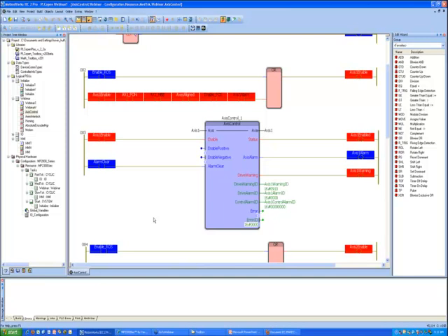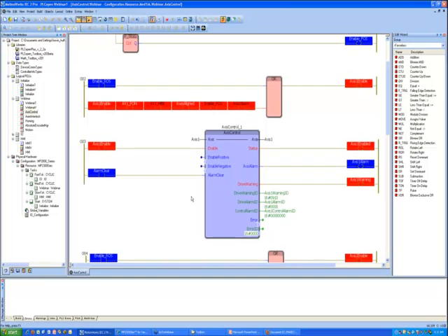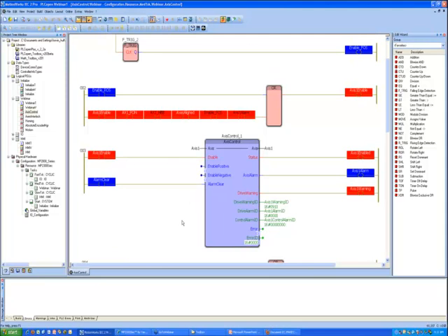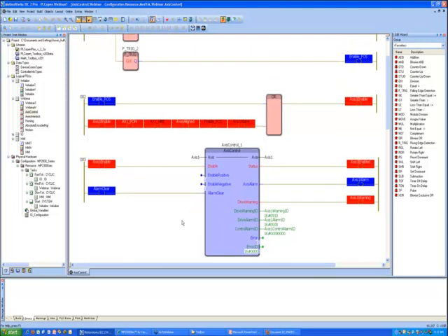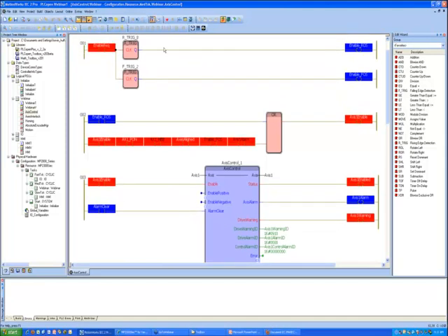And so I'm kind of demonstrating some of the other surrounding interlock logic that's useful for enabling the servo. So I've got some one-shots here that will enable or disable when I change the enable request. And then my logic will keep the access enabled as long as the power is on. This is a global status bit. And as long as the hardware base block is not on, that's the safety circuit, the CN8 on the SGDV. And a couple other things I'll talk about with other function blocks I'm describing later on.